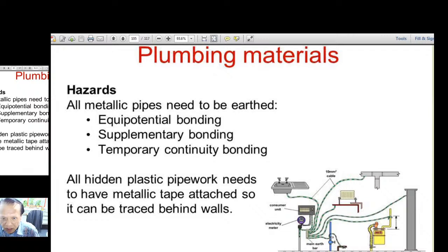Even the sink in the bathroom of the swimming pool must be grounded. Everything, any metallic parts of the swimming pool, must be connected to ground before any finishing is completed. This is to make sure that all metal parts are of zero potential.